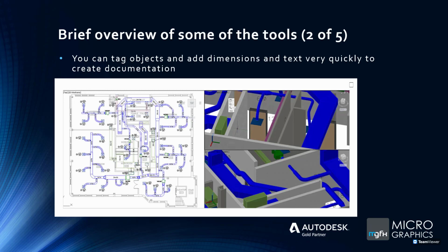annotate, and make sure that the annotations are correct, and the objects are named correctly. Right, and you can also see as an overview the planning and the routes of the components. The views on the right are basically 3D views where you can see heights and check if there are services that are clashing perhaps with your ducts.